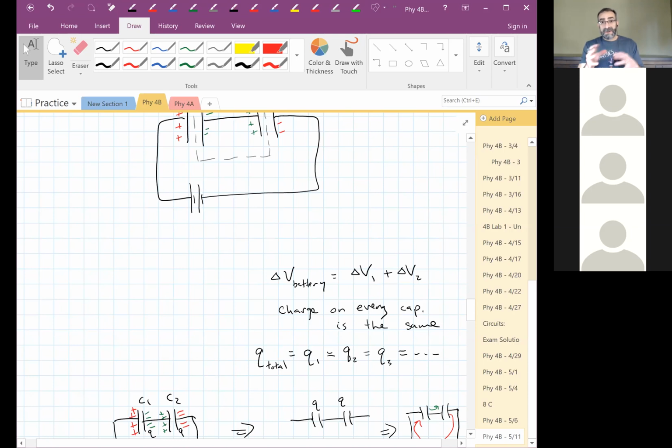Because of this weird thing with the charges, you can see the capacitance doesn't go up when we add more capacitors. The total capacitance actually goes down. So this is sort of like resistors in parallel, right? The more resistors we add in parallel, the lower the resistance was. So these add the way resistors added in parallel. So 1 over C equivalent is 1 over C1 plus 1 over C2 plus ...